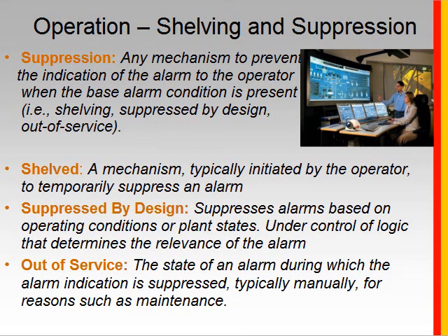And it's only on a temporary basis, which means it'll come back in a certain amount of time, 30 minutes, 8 hours, whatever. The idea is that the operator is trying to respond to an upset condition. He's looking at the alarms and he sees that some of them are less important than others, and he wants to get them out of his view temporarily. The idea that they come back means that they won't be forgotten.